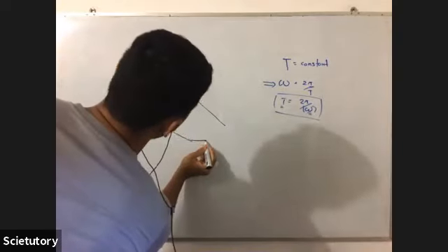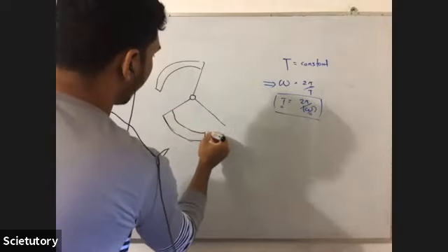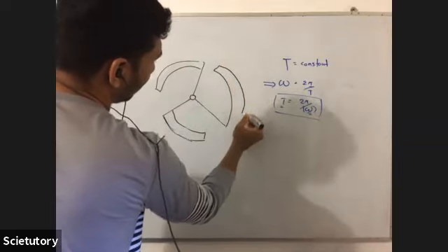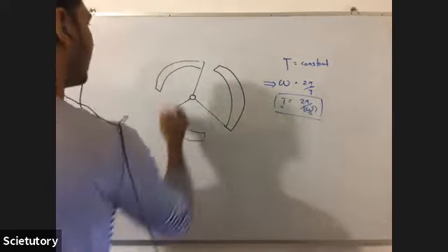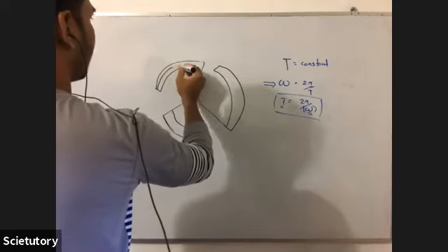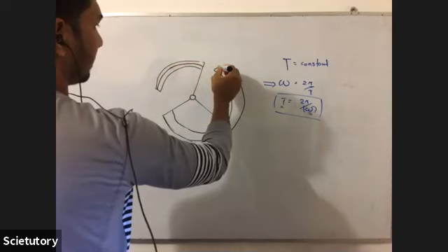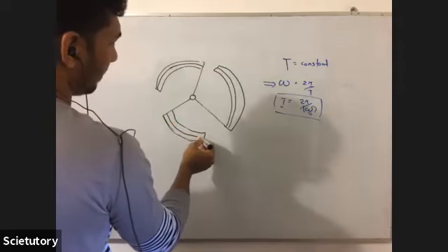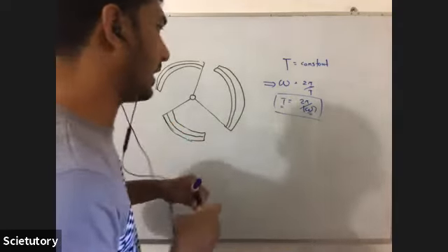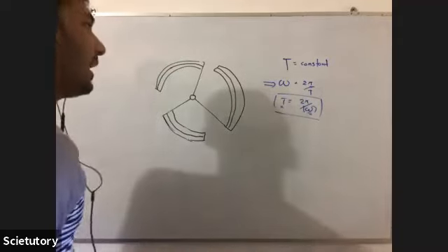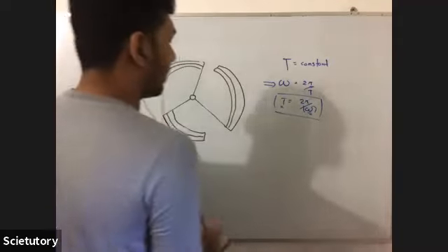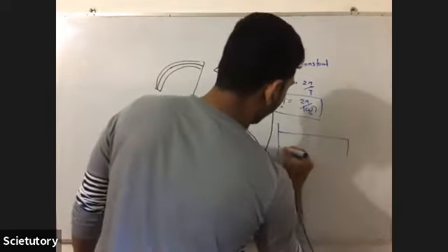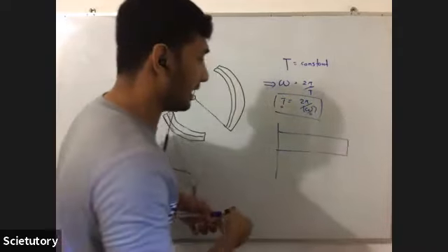There are bimetal strips. You people know about bimetallic strips, no? Used in iron boxes, and I only know iron boxes. Yeah, iron boxes. We learn bimetallic strips during O levels. One has a higher heat expansion and one has lower. These are like two strips joined together very firmly, attached to each other, and they have different linear expansivities. So when one end, one terminal, is attached and fixed, you can actually predict the movement of the bimetal strips with increasing temperature.